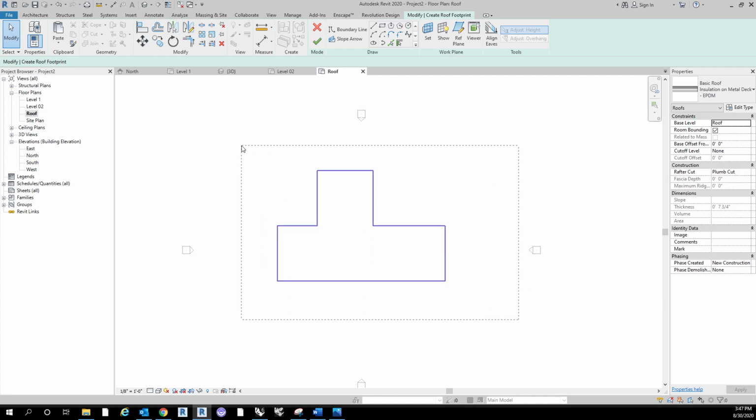And you can actually, if we delete all that, you can actually use that Pick Lines, and if you tab using the tab tool, and click a couple times, you can cycle through the different elements that are underneath your mouse. And typically, if there is a piece of geometry that has a completed boundary within that view, you can use that and it will highlight that entire perimeter so that you don't have to go through and select every single individual face to create that entire perimeter. All right, so now that we've done that, hit checkbox.